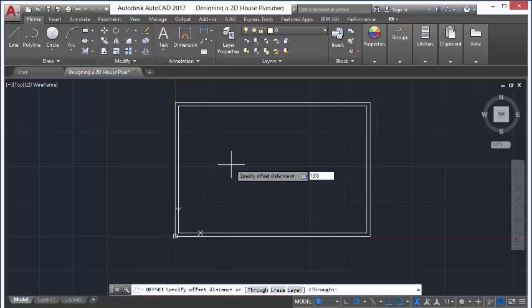So there is no need for you to put a space in between the feet and inches. When you enter 13 and follow with the feet symbol, which is the quotation, then you enter any figure after that. AutoCAD understands any figure after the feet symbol to be inches.